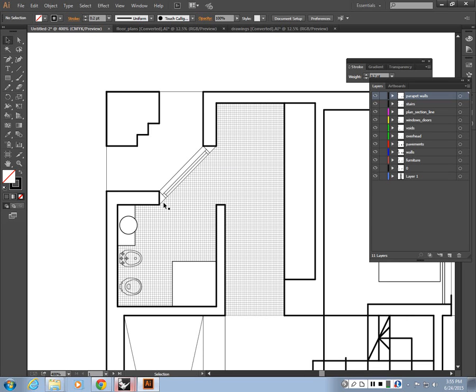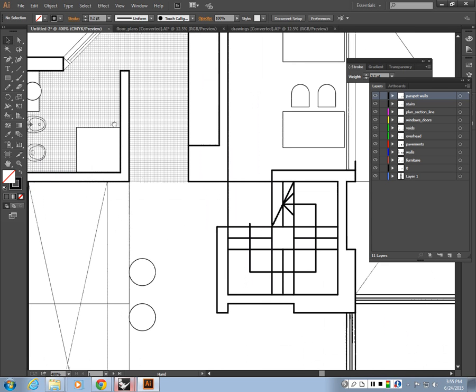So think of how we are looking at the floor plan. We cut through the building, we are cutting through the structural element, so we are seeing all of those elements already cut, so they should be thickest because we want to indicate that they are cut. And then we are looking down. So the first thing we see after that is the furniture, and then we see the floor tile, right? So the floor tile is actually the furthest away from me in my view when I look down on the floor plan, right? So in this case, stairs could be thinner as well.